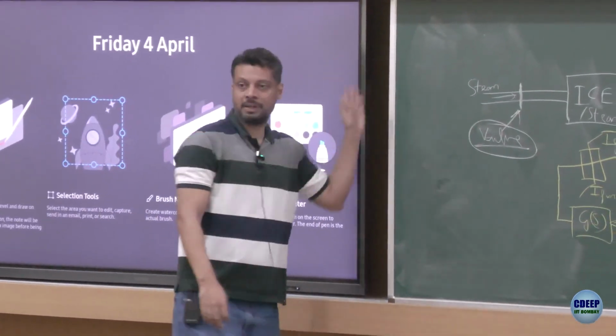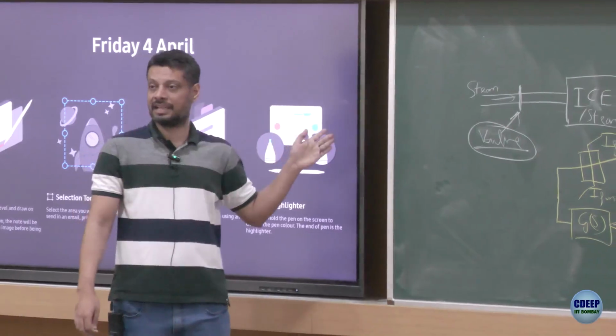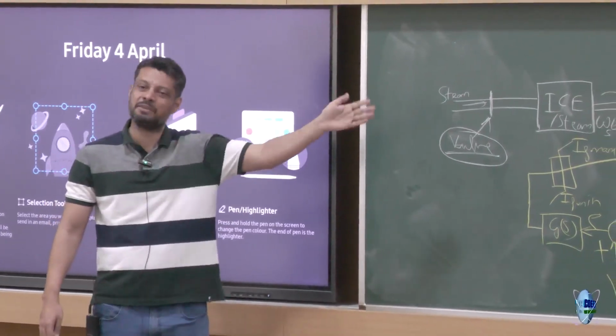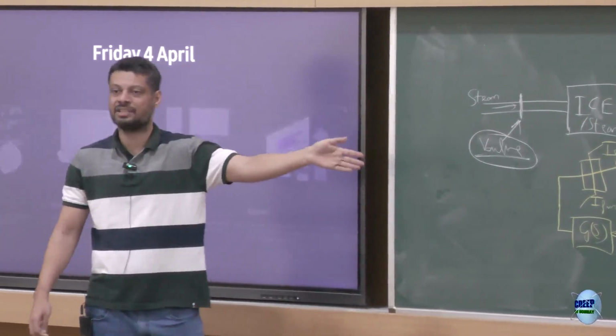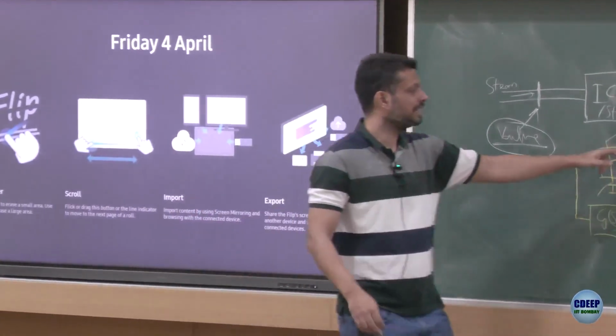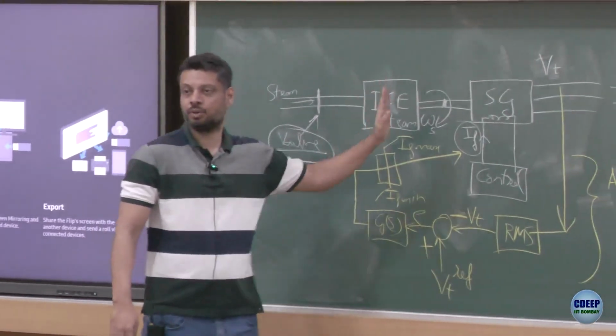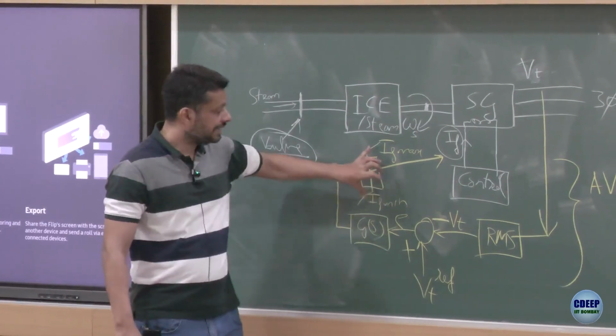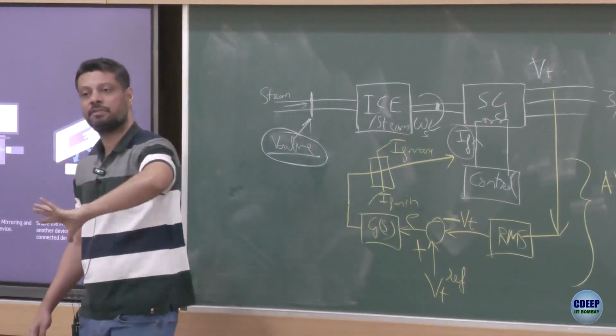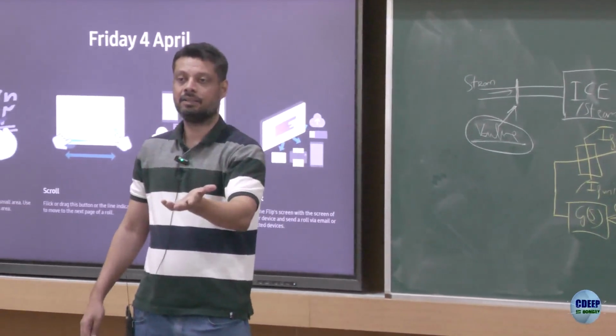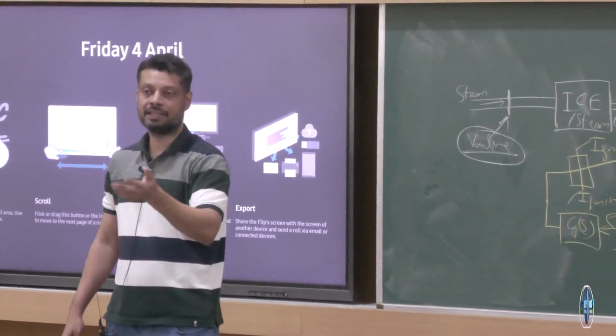So you saw, right, B versus H graph, E versus IF, after a certain point, even if you increase IF, it doesn't make any change in the EF. So you don't want to keep increasing IF unnecessarily, right. So you can limit the values. In this range, you know that if you increase IF, your VF will increase. Not proportionally, but it would increase, right.